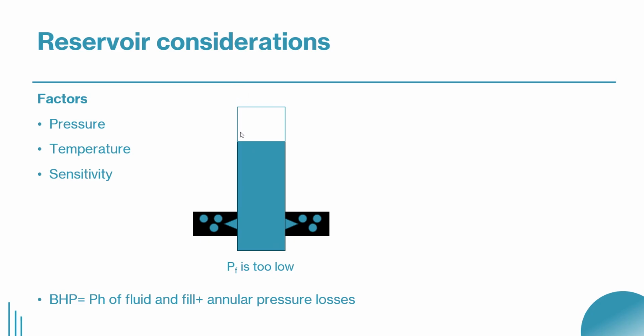in this case, you can use any material that can temporarily block the formation, like, for example, a non-damaging salt plug. You can place it across the perforation, and in this case, you can maintain fluid level at surface because the salt plug will temporarily block the perforation. This is the first case.